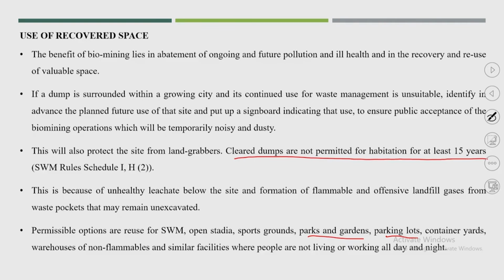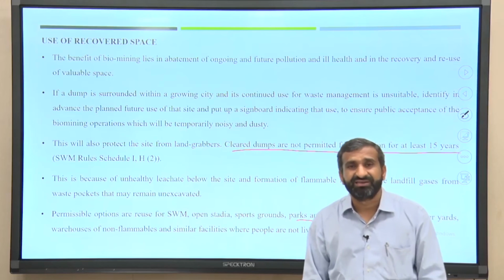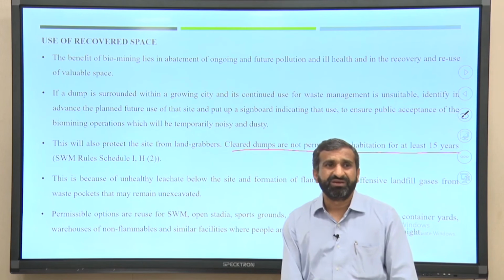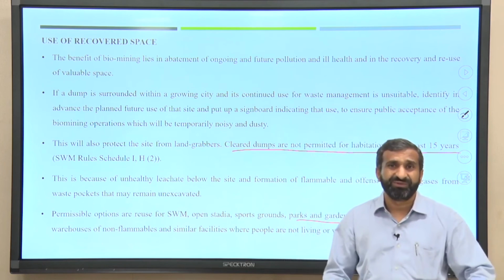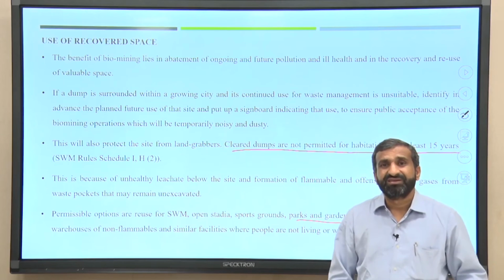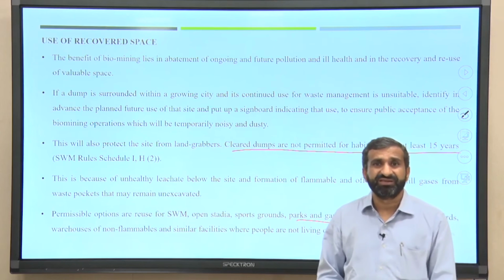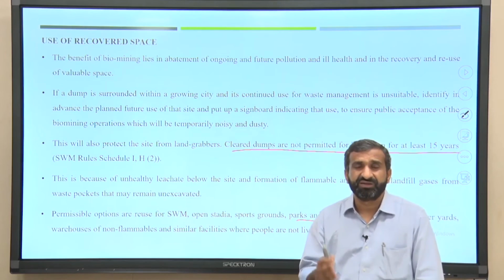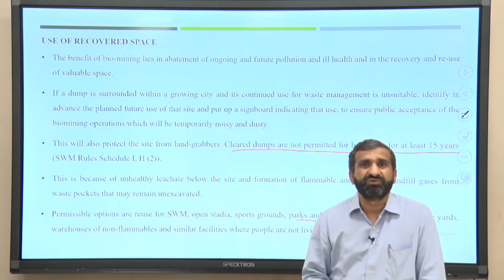And it is good to grow something in that area, maybe a park is the best idea or a garden you can make, but for the initial period also do not allow the local people in that garden, at least wait for 5 years, or from time to time collect gas samples in that particular area, and also check the groundwater from time to time.